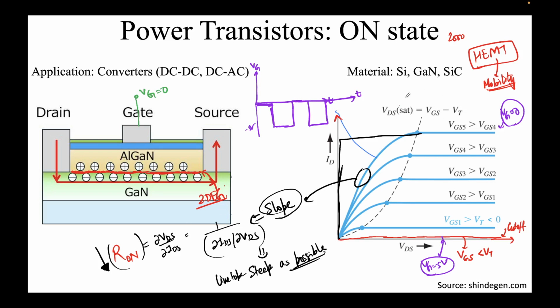So essentially, if you recall the expression for MOSFET, the ID, right? Mu n C ox W by L Vg minus Vt whole square by 2. I'm talking about the current in saturation. So it depends on mobility also, correct? And so mobility, I told you, is usually higher for HEMTs rather than silicon based MOSFETs, right?